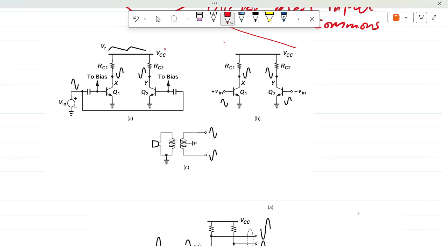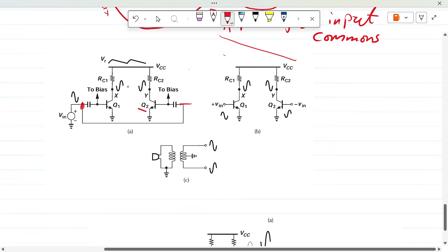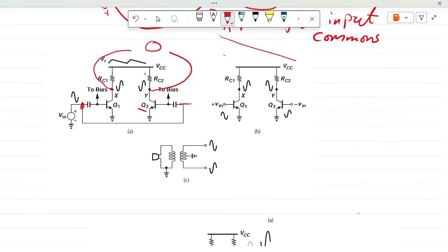Assuming that previously we wanted the transistor Q2 not only to help us in noise cancellation but also to help in boosting the signal, and we connected Q2 also to get part of the signal in an attempt to amplify it, then we realize that at the differential output we were going to get zero output, because the differential pair was going to reject that common input.